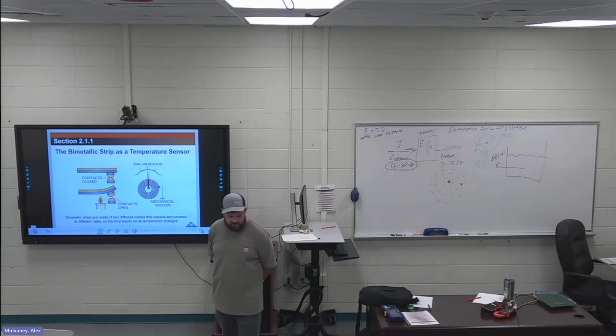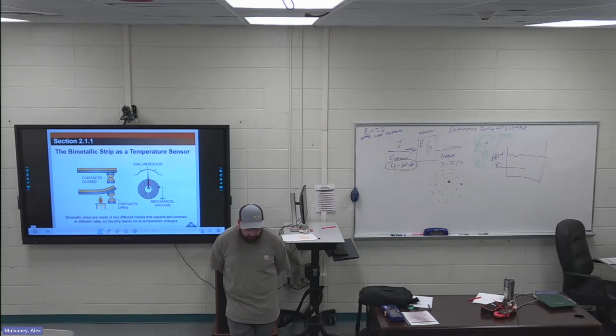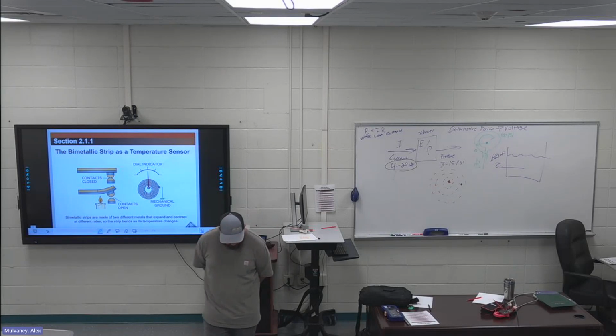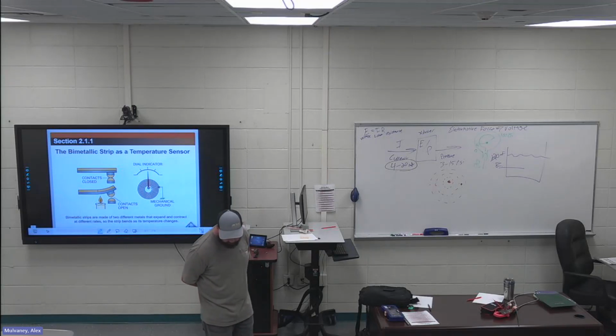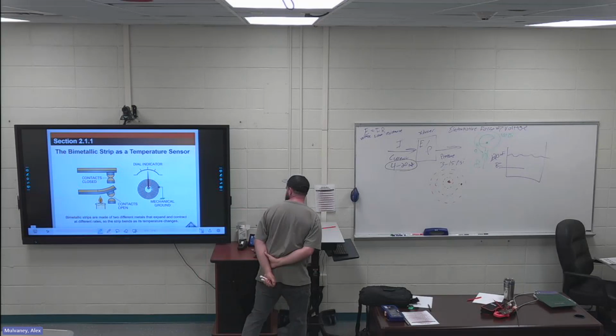Temperature detection, bimetallic strip thermometers. The first 3 sentences are highlighted. A bimetal element, figure 10, is comprised of 2 different metals bonded together. One is usually copper or brass. The other is a special metal called Invar, which contains 36% nickel.